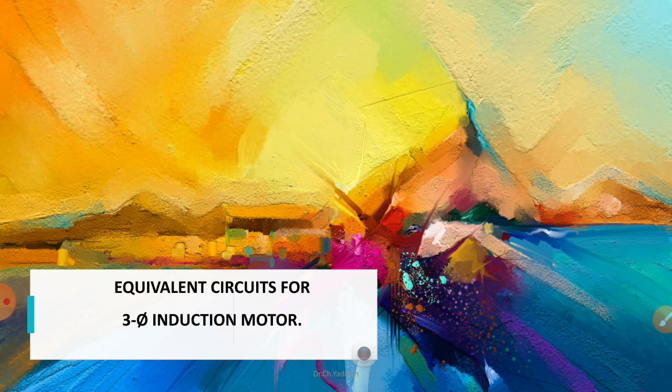And you know that whenever the AC supply is given to the primary winding of the transformer, it establishes its own magnetic field in the primary coil, and this produced magnetic flux is alternating in nature due to the AC supply, dφ/dt. This change in flux links with its own conductors, the primary conductors.